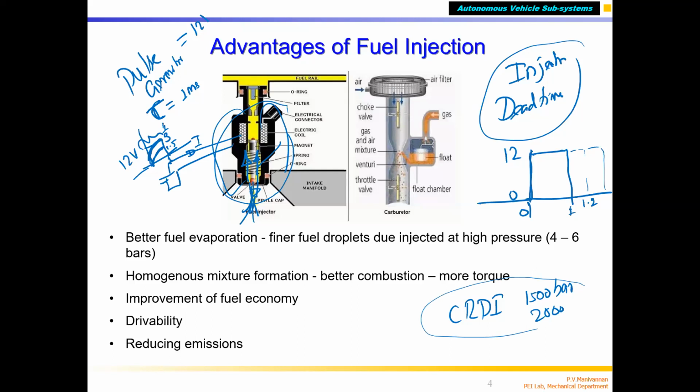Sometimes students and research scholars do it without knowing the consequences. You won't even have pain. At least if you go to a doctor and get an injection with a needle, you have the pricking pain. Here you won't even have that, because the fuel comes out like a mist, around 5 micron in diameter, at 1500 bar or 2000 bar. It deeply penetrates into the bloodstream, blood vessels and muscle. You can't remove diesel from your body; that is not so easy, correct?